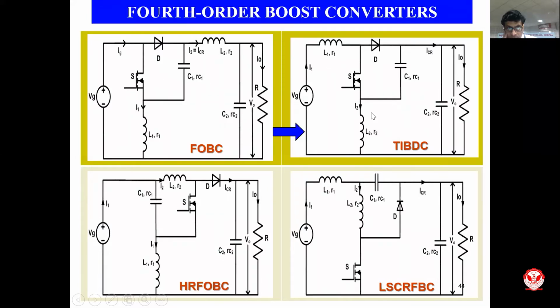the load. So the second converter, if you see, is formed by changing the position of the inductor, which here was at the load side. Now this inductor is placed at the source side. So only one change is done, and this changes the characteristics. So you have the possibility of placing it at the load side, or at the source side.